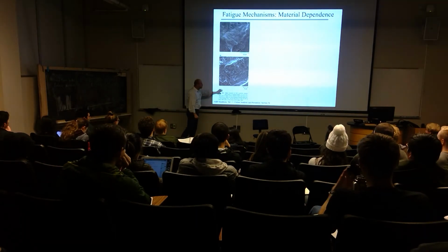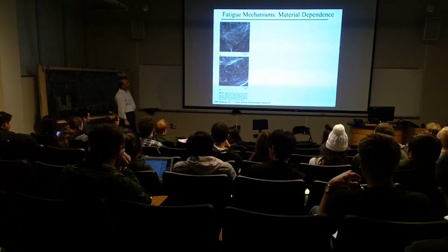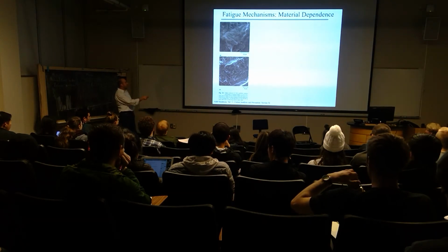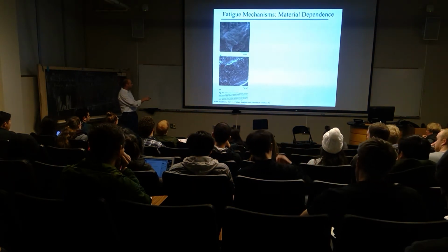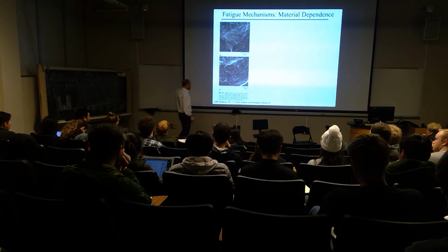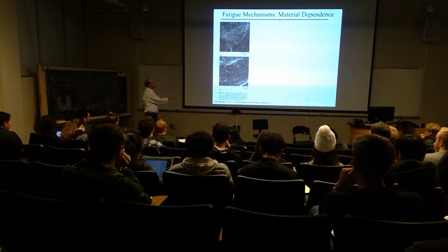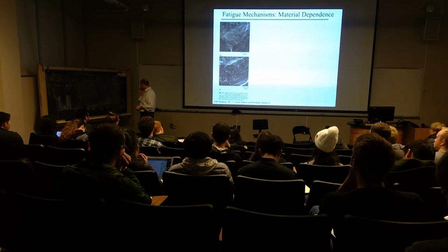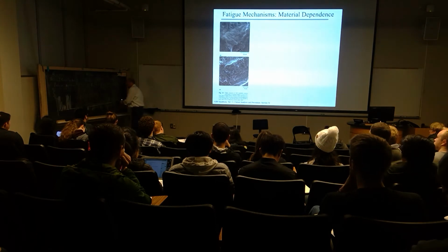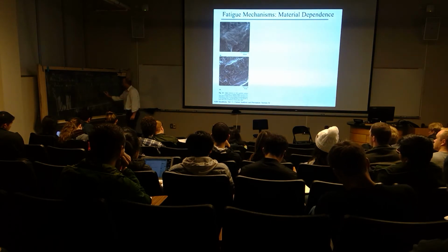So, there are some good examples in your handbook. Figure 33 shows some examples of striations in 18-8, often stainless steel, under rotating bending. It shows you in A some very fine striations that were in this particular material. It says midway between origin and final overload fracture, okay? So in this case now, the delta K was smaller. So how do I know that? I want to make sure that you see this because this is an important part of you connecting the science to the observation.